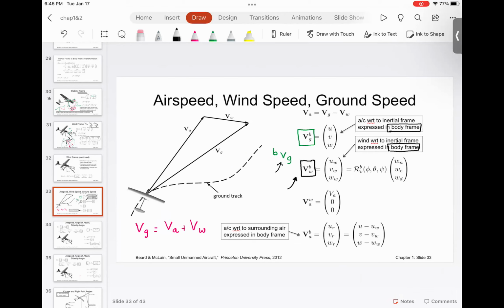Now, it is important to know that velocity in the body frame, I can transfer onto the inertial frame using this rotation transformation. I want you to understand, this is body R and this is vehicle frame. Remember, vehicle frame is aligned with the inertial frame.